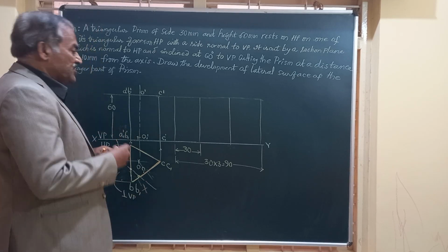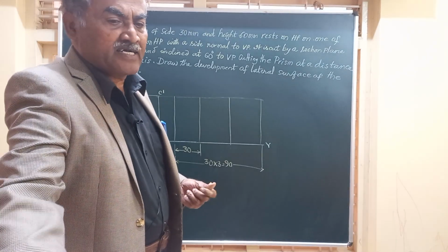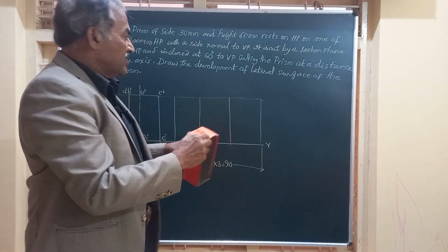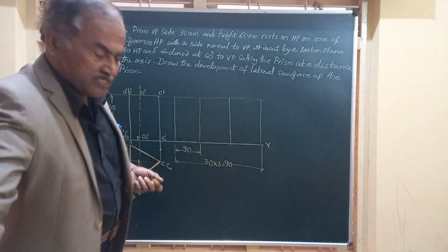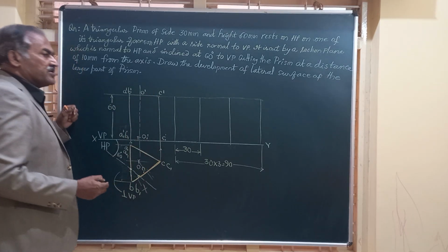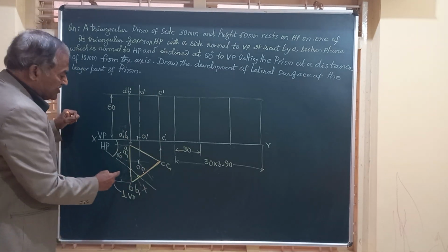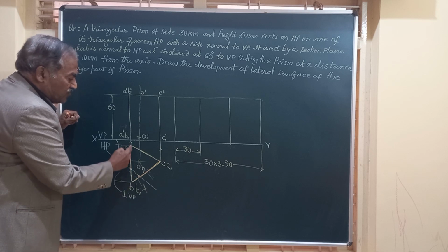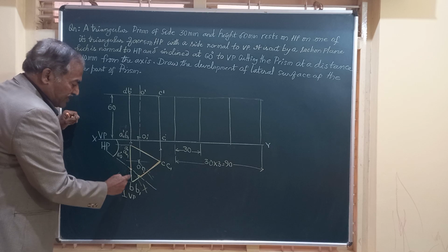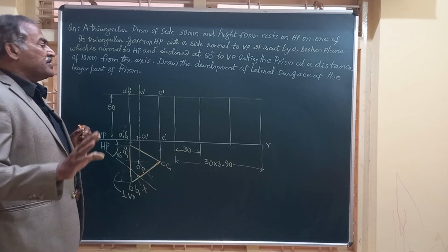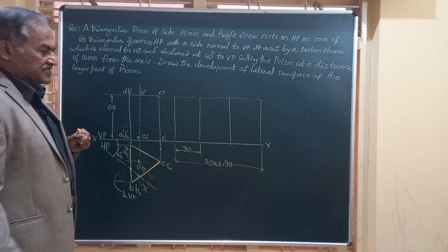And you can see here, when the object is cut like this vertically, it is going to cut both the top face ABC and the bottom face A1, B1, C1. So here you will have 2 points, 2 for the top edge, 2 for the bottom edge. Here also 2 for the top and 2 for the bottom. Totally there will be 4 points.